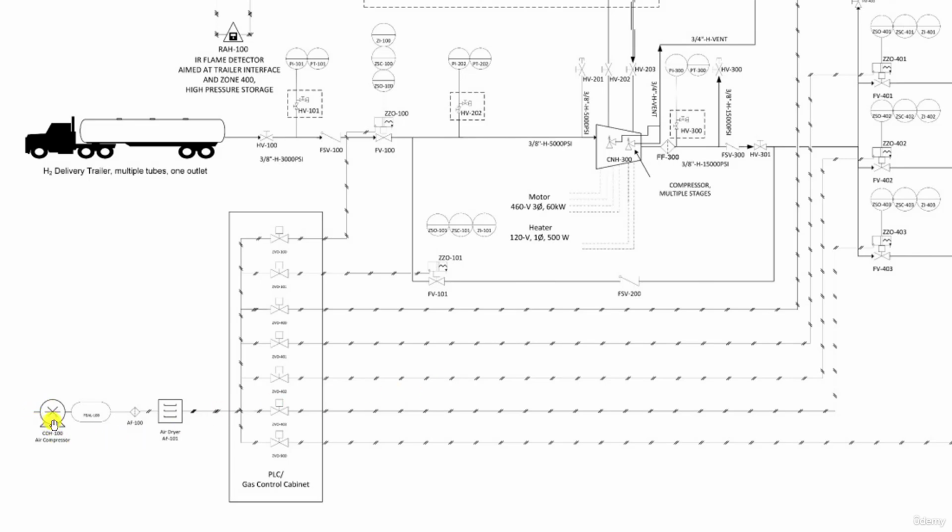The first equipment in this system is an air compressor. From the symbol, we can guess it is a liquid ring compressor, so a positive displacement compressor. The compressed air feeds a surge vessel PBAL100, then a filter AF100 to trap all residual materials and purify the air.